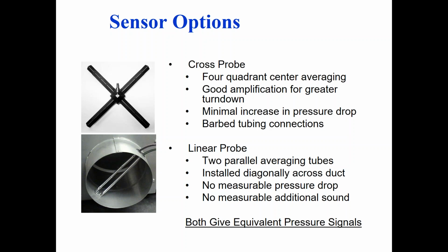The manufacturer of the VAV box provides the cross flow along with a couple feet of pneumatic tubing that go over to the control box, and the controls guy can mount his controller in there, which has the actuator, the heat stage relays, the communications, and a pressure sensor on there.